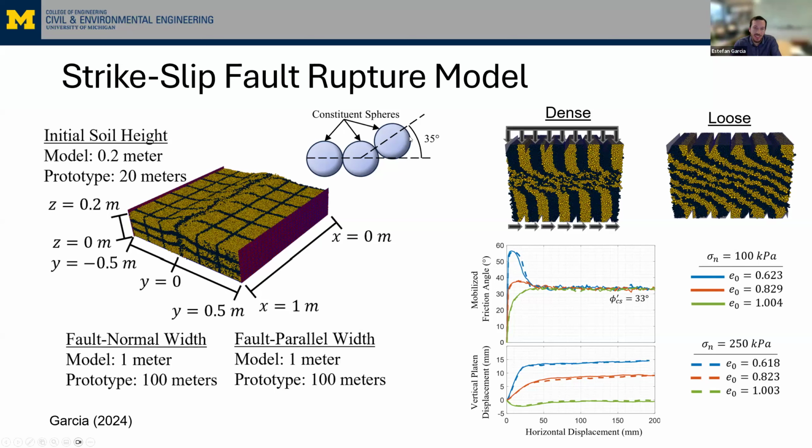widespread. And by using some simple non-spherical shapes that at a minimum capture inhibition of rolling about all three Cartesian directions, we can further capture mechanisms of grain interlocking that contribute to soil deformation behavior. And we take this method at one scale here and upscale it to the scale of several meters, which we do in this model by applying an acceleration due to gravity of 100 Gs, as one does in a centrifuge experiment, to represent the stress associated with several meters of soil, in this case representative of a depth of 20